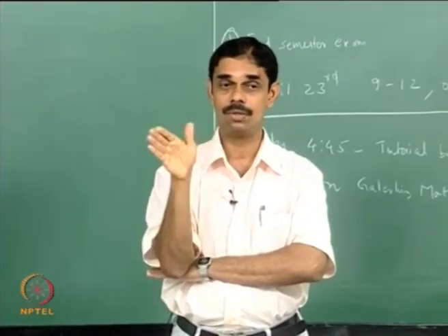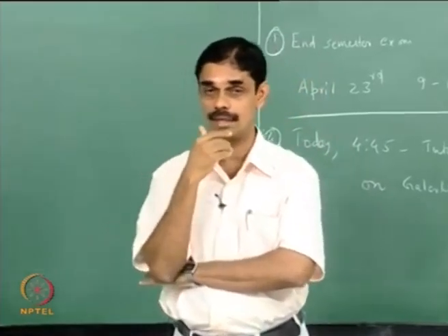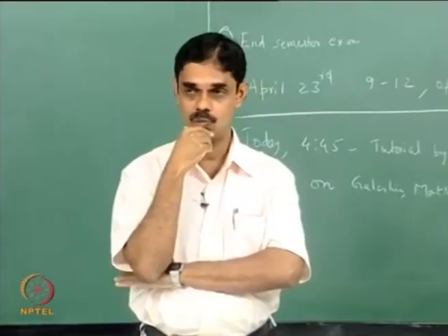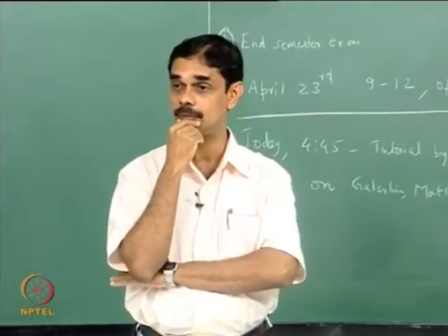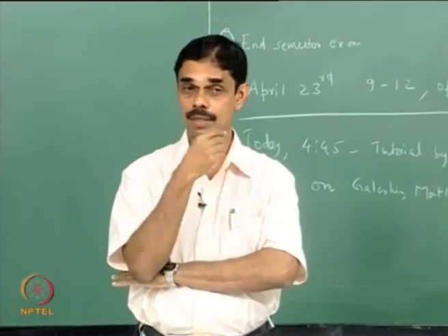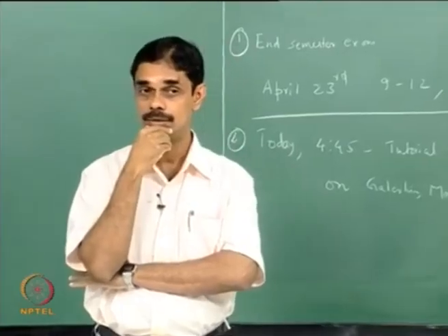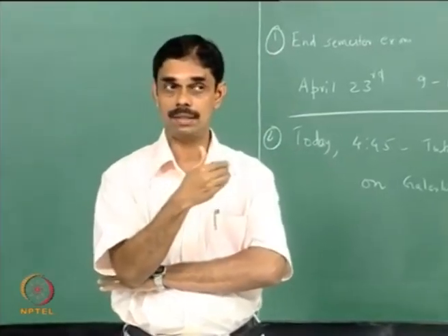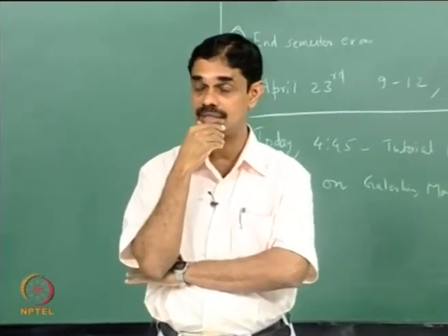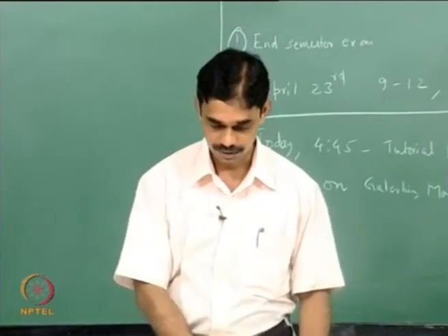Instability. When you go to lower and lower limits, the NOx reduction performance is very good, but then the flame speed is starting to be a very strong function of equivalence ratio, and the ignition time delay is getting bigger and bigger. So these now make conditions very conducive to forming thermoacoustic instability. So that is what we will talk about.